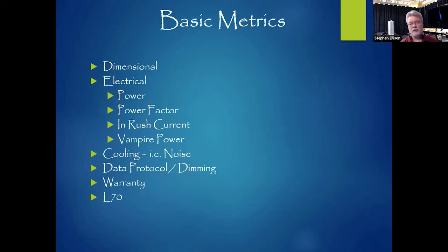0 to 10 dimming is one method, but you lose control. You don't get all of the control. You're going to do a group of fixtures instead of individual fixtures. Then you're also not going to get down to 0. They're going to blink at some point. So I recommend, if you're doing something that's got control, put in DMX, because you can guarantee you're going to get a good theatrical dimming curve.